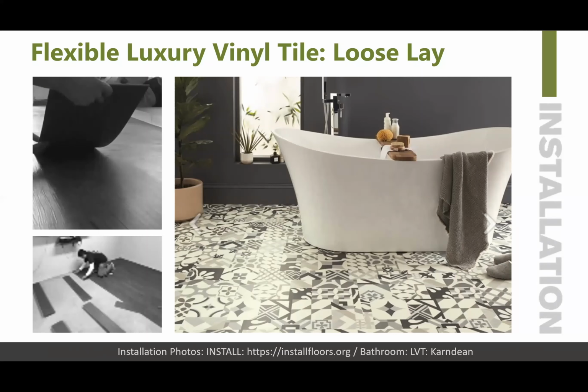Loose lay is ideal for raised access floors. There are some restrictions to this as well, but for the most part, loose lay LVT can easily be installed over most raised access floors, especially those that may require frequent access. Loose lay has a higher sound rating than traditional LVT. Traditional LVT typically will not contribute significantly to sound reduction, while loose lay LVT is a thicker product with a textured back that offers improved sound testing results, helpful in corporate, multifamily, or other hospitality installations.